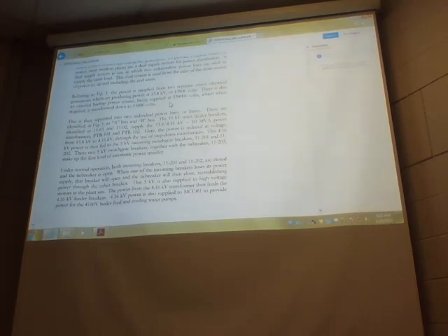The 15 kV main feeder breakers identified as 1101 and 1102 supply the 13.8 kV to 4160 volt, 10 megavolt-amp power transformers PTR 101 and PTR 102.